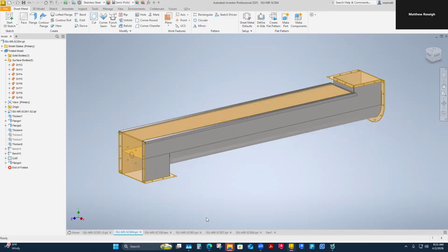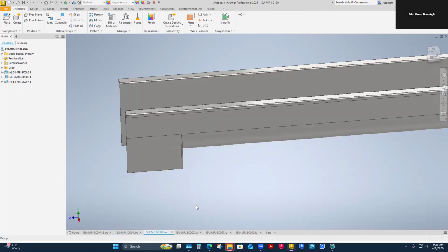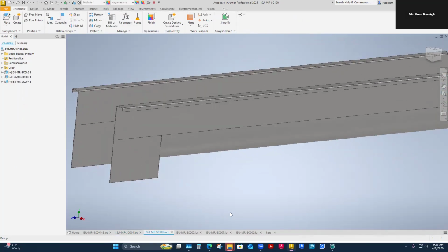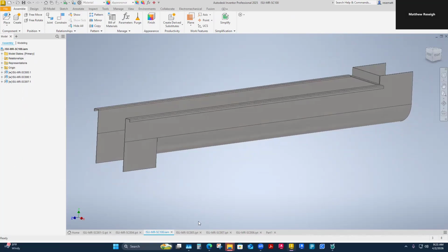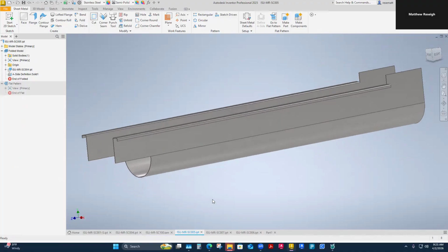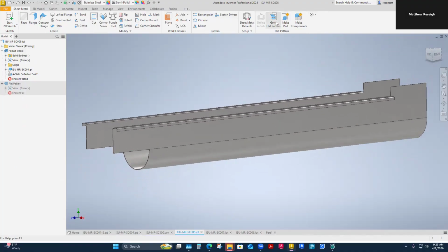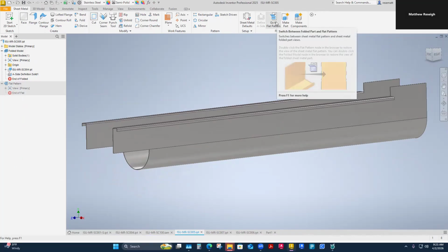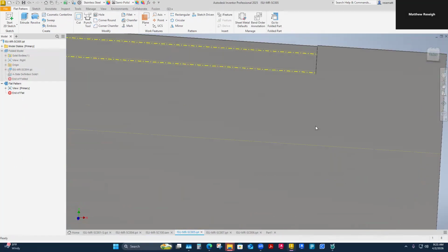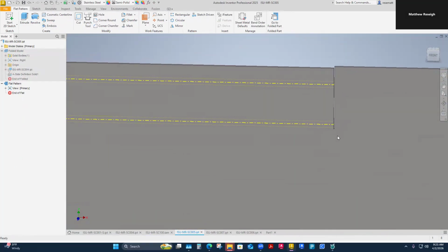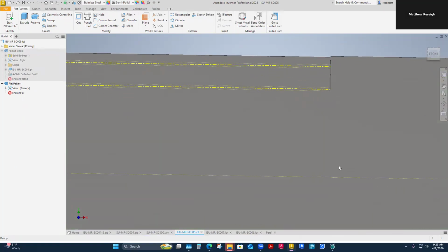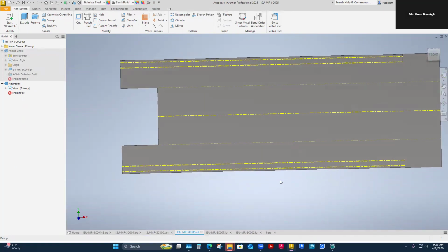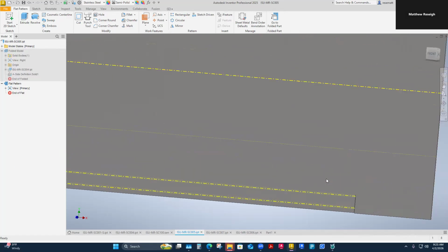But that's all I wanted to get to here. Now I want to check those three parts. I have my assembly open, and I just want to open each part and make sure they're updated. I'm going to go to my flat pattern and check it. Your main housing should look like this now, with my slit cuts that are going to help me bend it. That's critical: you need a relief cut in order to bend those flanges out of the same part.